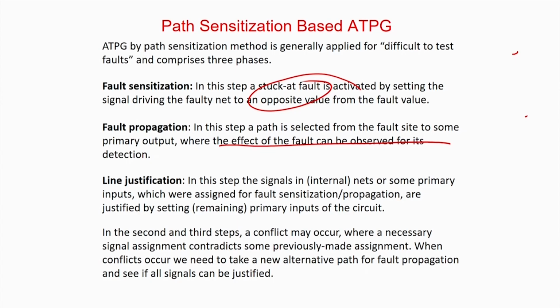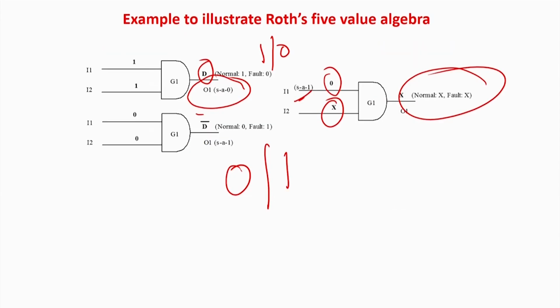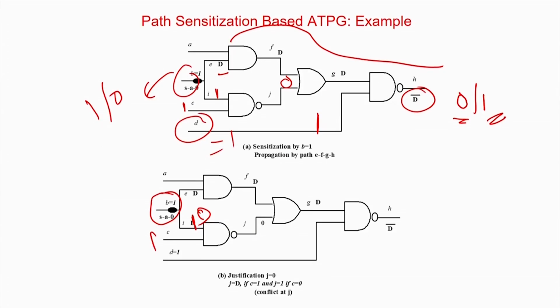And as I told you, in traditional circuits our job was to get 100% fault coverage. That means some of the faults will be covered in a random manner and whatever remains will be handled by this ATPG approach, where you target each individual fault and find out in this manner, so that we get a very high amount of coverage. But when you move to the SOC NOC level paradigm, even this will be blowing up, because the number of difficult faults will also be higher.